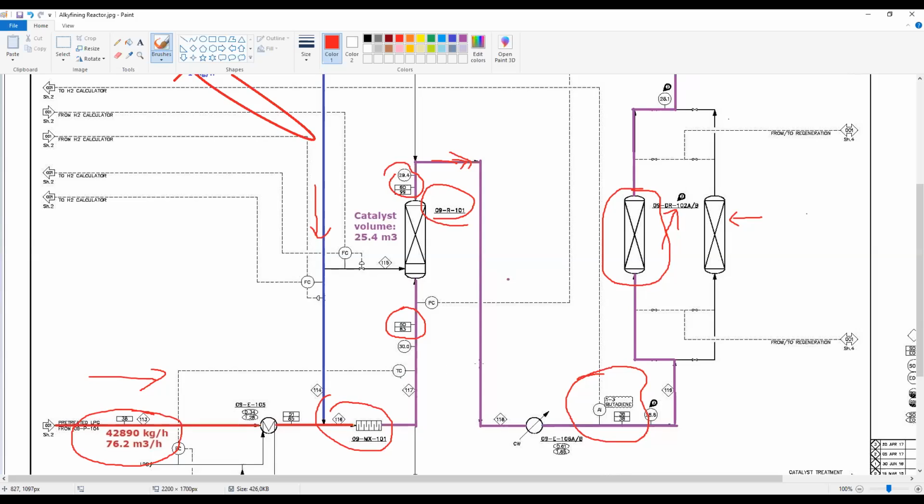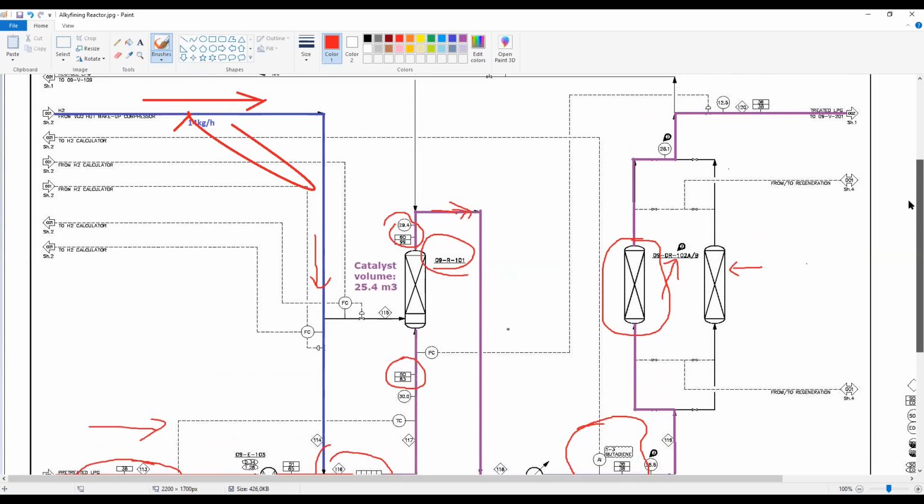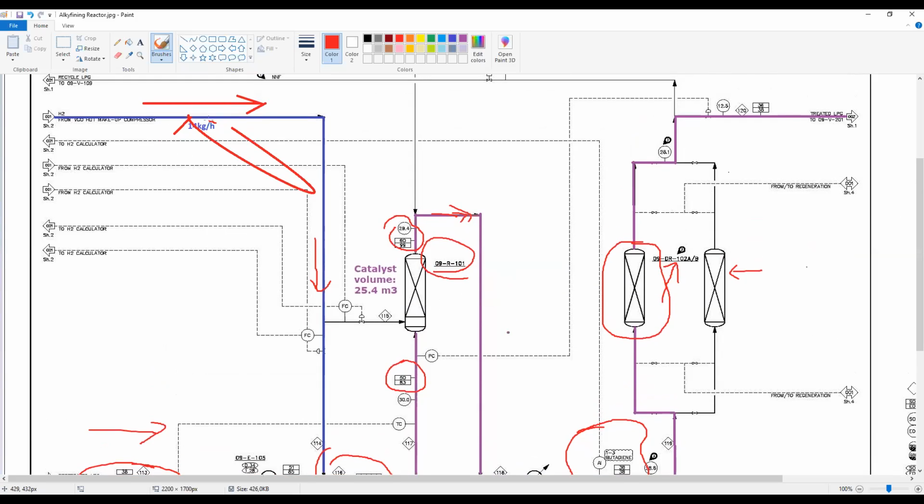Of course, remember also that I told you that during the startup aroma condition, you add more or less 14 kilograms per hour of hydrogen. At the end of run, you will have to add more hydrogen. The other quantity of hydrogen, you will add it directly to the reactor at the end of run conditions. And it is shown here at the bottom of the reactor that you will also have an inlet of hydrogen, okay? That is the stream 115.